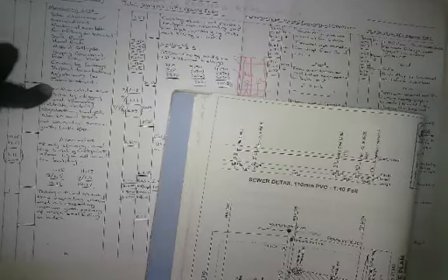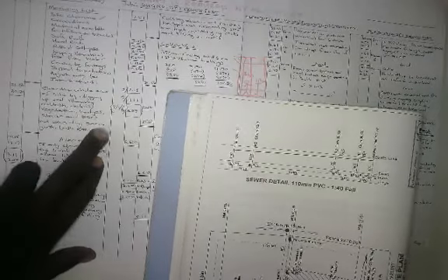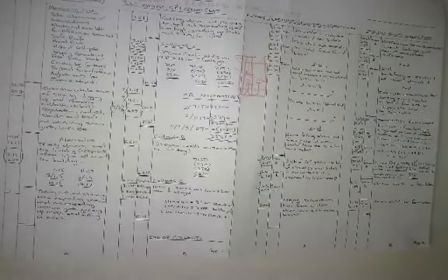That is also in your standard system. Remember, if a tree is a smaller tree and the girth of the tree doesn't exceed 200 millimeters, you won't measure it separately, because it will fall under your clear the whole site description, because it includes all trees that don't exceed 200 millimeter girth. Okay, guys.